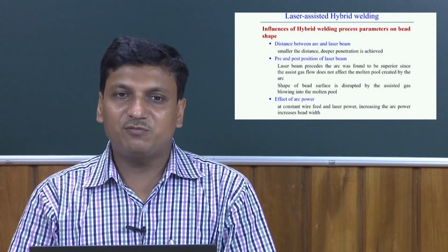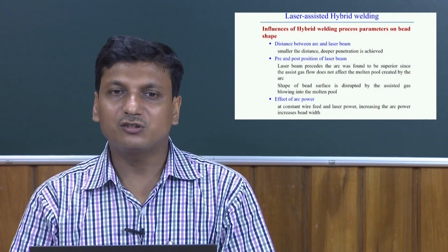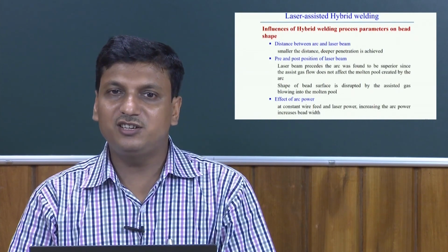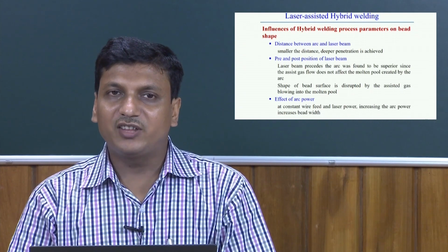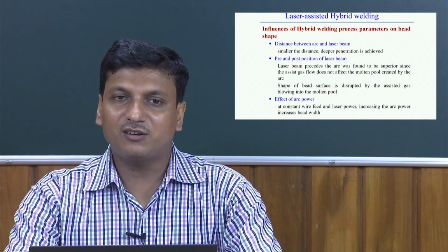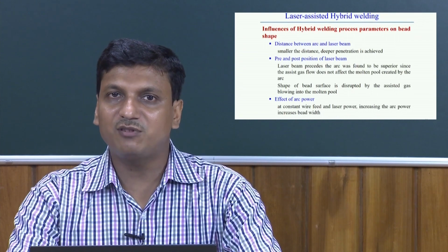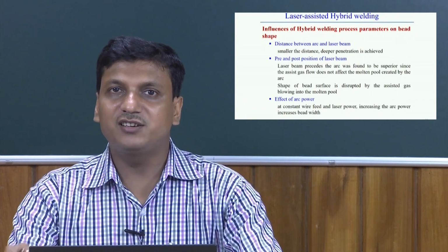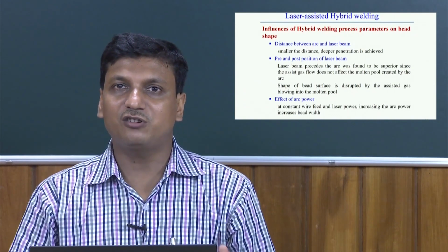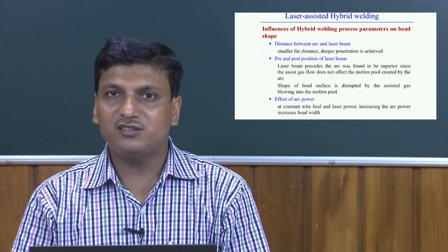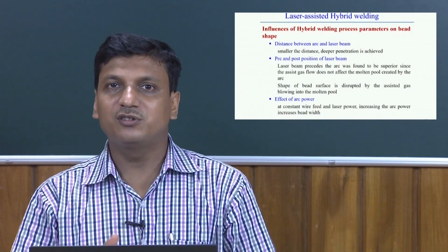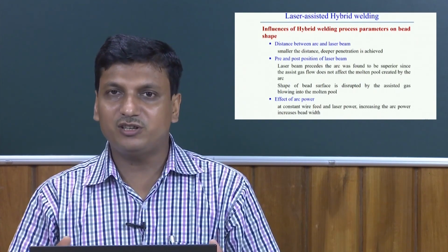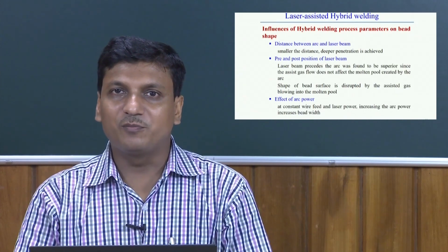Another effect of the hybrid process is the effect of the arc power. So, in laser assisted GMAW process, keeping a constant wire feed rate and a constant laser power, increasing the arc power actually increases the width of the weld zone. That is also obvious, because the arc power in this case helps to create a wider weld pool volume.